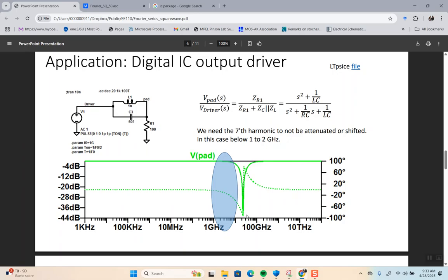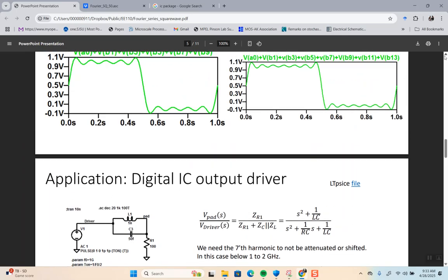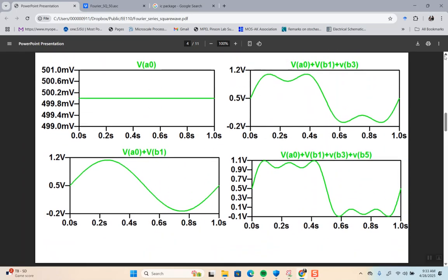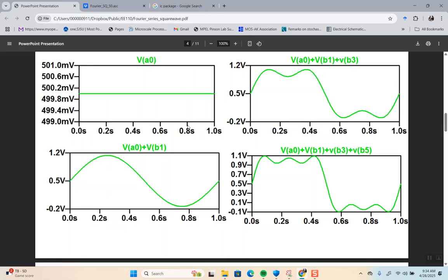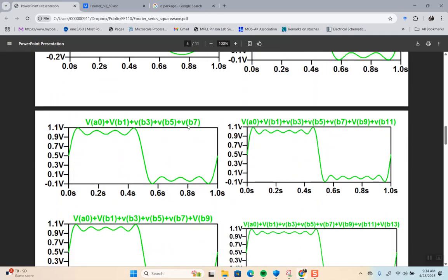And so those harmonics are needed to get the full digital signal. Because think about it. That could be a digital signal. You could interpret anything above 0.5 as 1, anything below is 0. So you could get data out of that. But again, with all the noise, you would need like a Schmitt trigger.